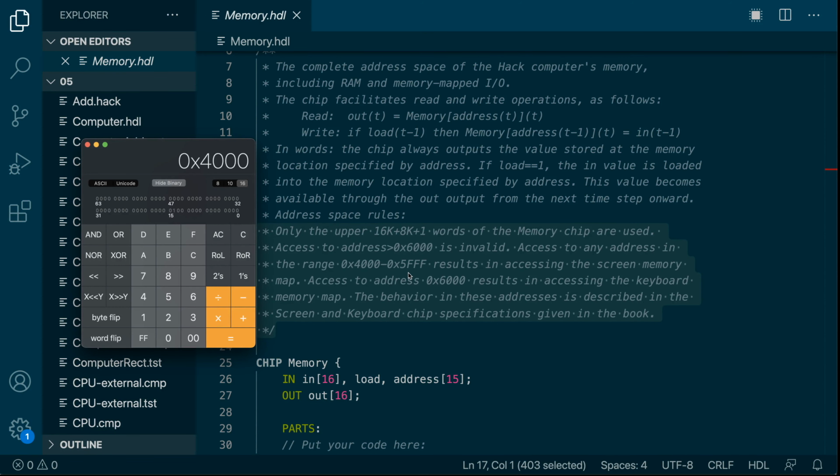And then we've got this 5FFF. Let's look at that. Let's actually do this right. 5FFF. And looking at this 14th and 15th bit, we see they're 1, 0. So those are the things we're going to need to distinguish on, is these two bits.